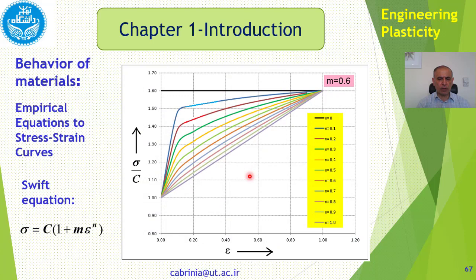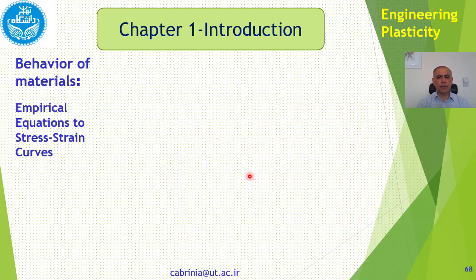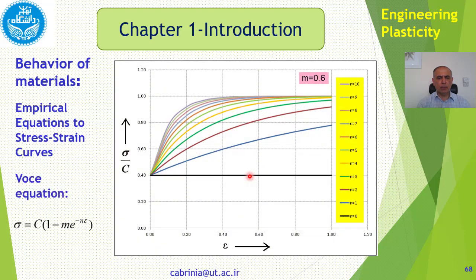Swift equation is another one which is very much used. Voce equation also is the famous one. As you can see, all of these start from some points in here. It means that they just simulate the plastic behavior of the material, and not the elastic. We don't have the elastic parts in here.